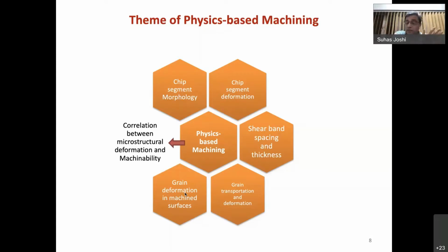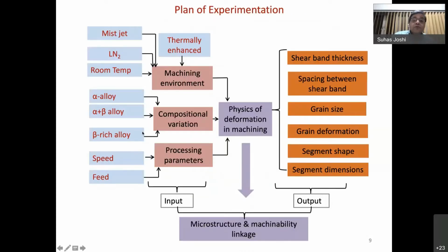If you gently remove the material, you will find that the machined surface is also not damaged. That happens in a diamond turning machining operation. You remove the chip so gently that there is no damage to the machined surface. But if you use a huge force, there is going to be huge damage on the machined surface. So what is that, and how do you prevent it?